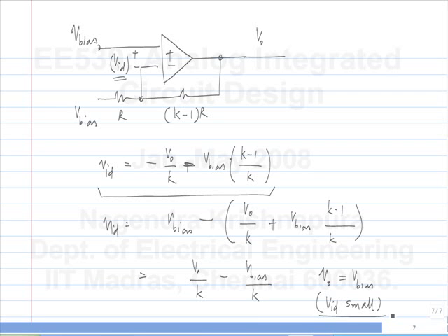So we'll continue this. I think the last part looked like it was not very well understood, but we'll continue this in the next class. But the bottom line is that every op amp needs to have DC negative feedback around it. Okay. So if you have a circuit with multiple op amps, you have to work out that every op amp has DC negative feedback around it. The negative feedback path can be through passive components, can be through active components, but whatever it is, for DC, you have to have negative feedback. Okay.